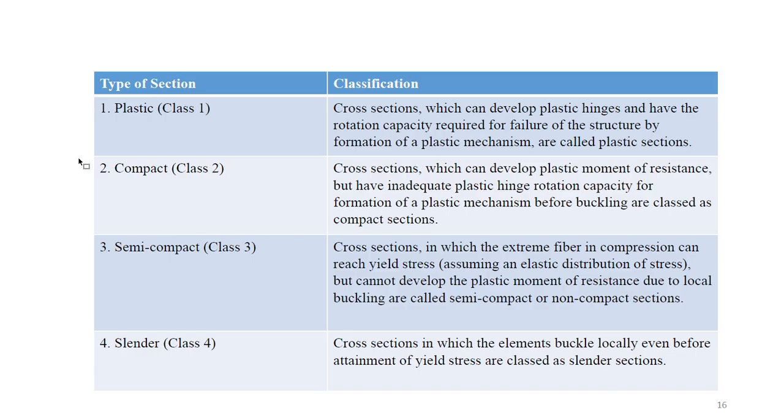To fail that one, it requires another extra hinge. If you take any fixed support condition with a single hinge, a single breaking point, a single yielding point, the structure is not going to fail. If it forms an additional hinge, then the structure is going to fail.